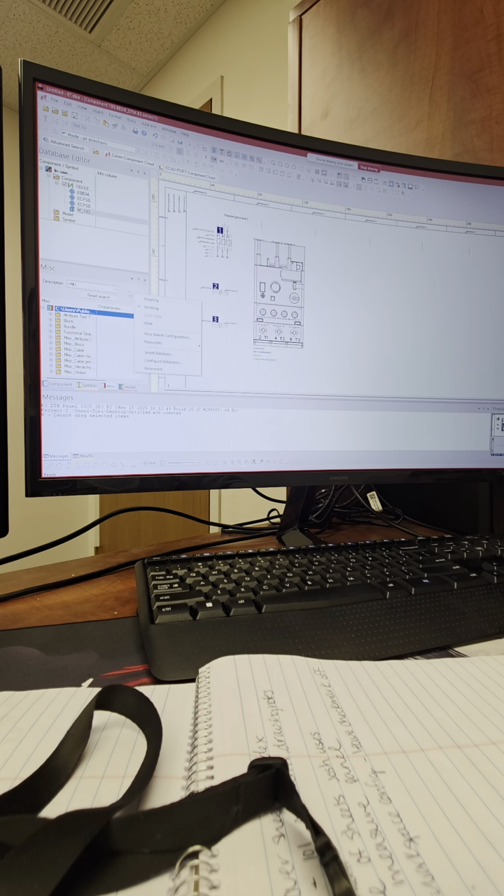Looks like it's missing the actual symbol name feature as well. Right click, search configuration. And this will be your symbol name that I was trying to think of. Symbol name. And add it to the right. And then change the order of these two by using the second list of buttons on the right side, that shows up and down. Okay, that looks proper. Symbol name comes first. Click OK. All right, and click on symbol.